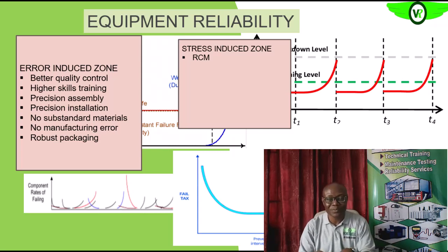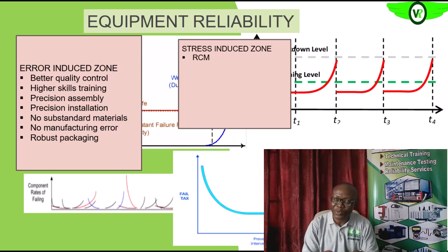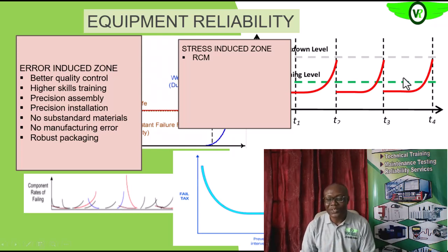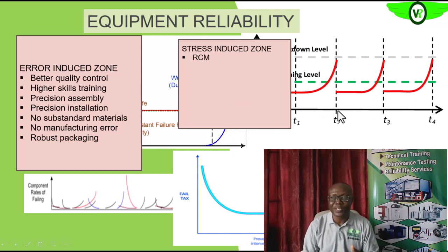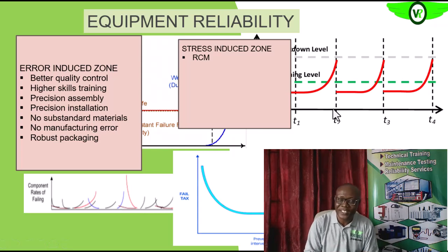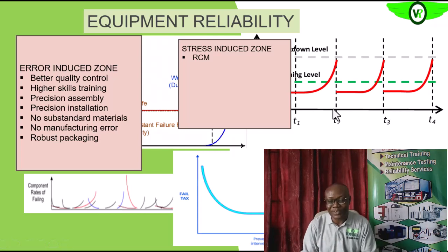Those that it is less feasible, not economical, to run to failure, we want to see how we can do a preventive maintenance program on them, that is a time-based maintenance program. Then those components that we feel can be replaced when they still have useful life in them, or can fail before the PM program, we can deploy condition monitoring on them.